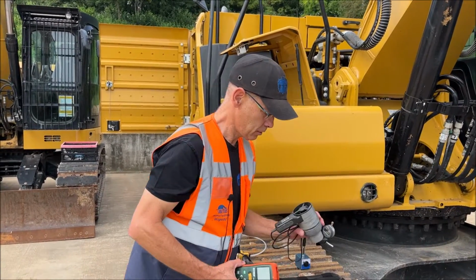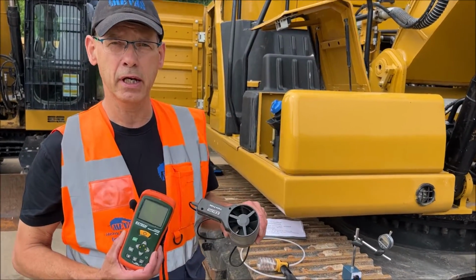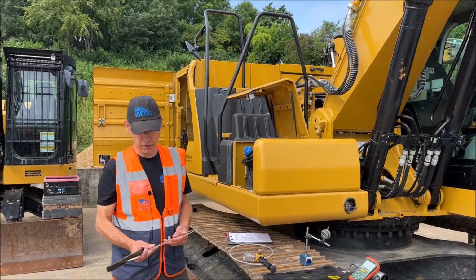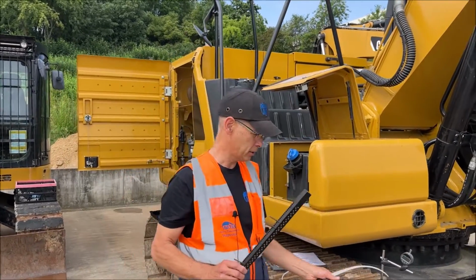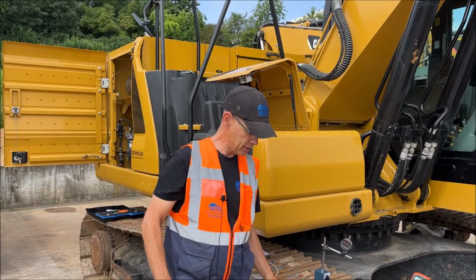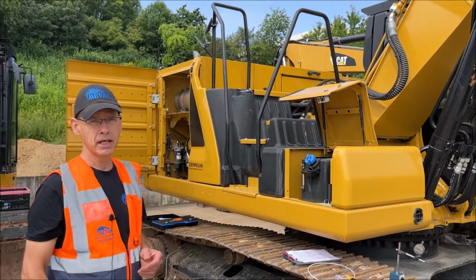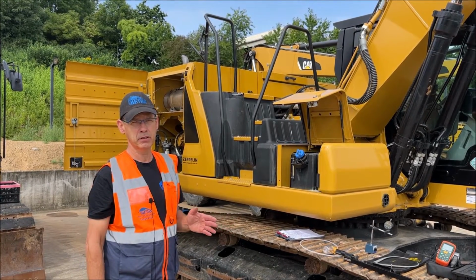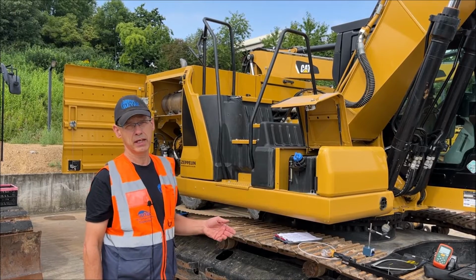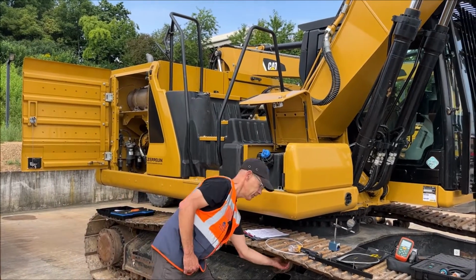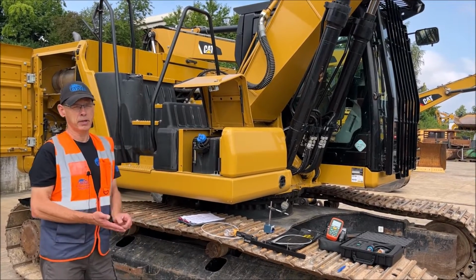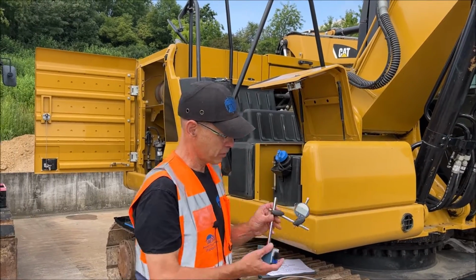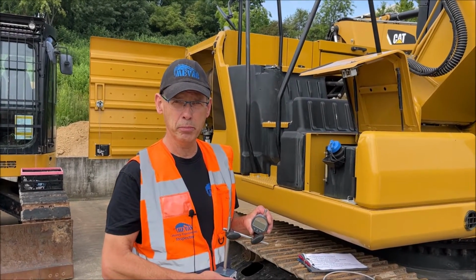If required, the inspectors can use an ionometer to measure the blow-by of an engine. When it comes to undercarriage, we have the tools to measure undercarriage. On small machines like an excavator of this size, we usually do an estimation, and over the years the inspectors gained a lot of experience, so just from touching the bushing we can estimate whether it has 80 or 60 or 40% remaining life. We have a gauge to measure the swing bearing play.